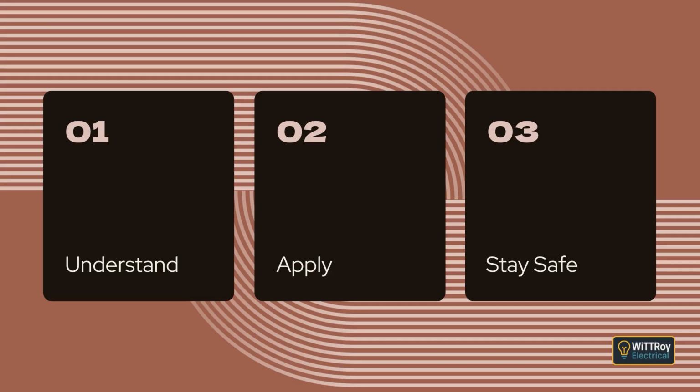Clause 3.9.7.2, Insulated and sheathed cables. Armored sheathed cables may be installed in concrete or plaster or cement render without an extra wiring enclosure, provided they meet all installation requirements for mechanical protection. Unarmored sheathed cables installed in concrete must be enclosed in an appropriate wiring enclosure that meets the rules for concealed wiring.